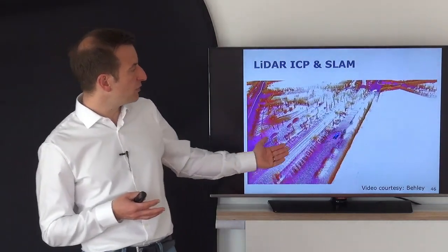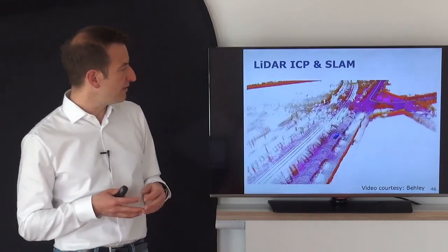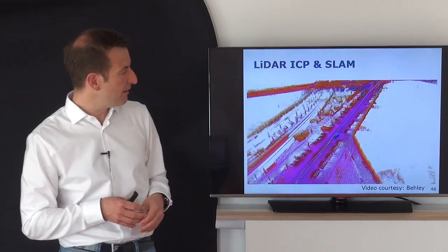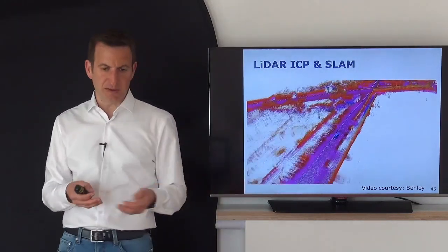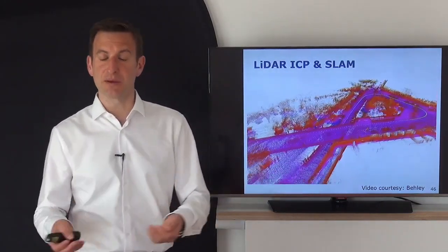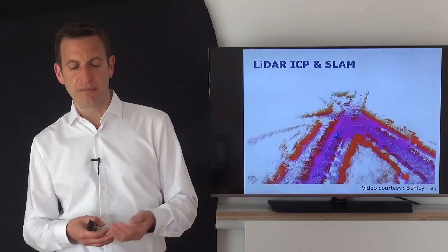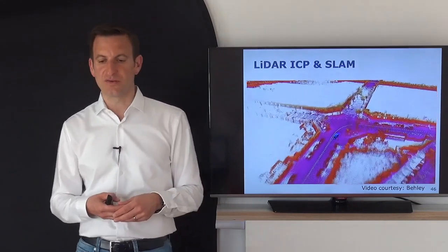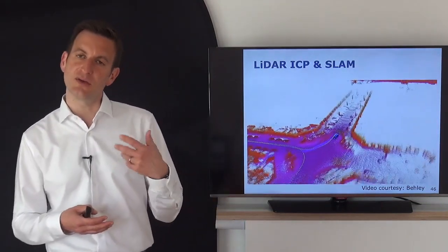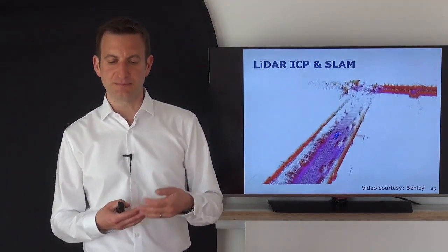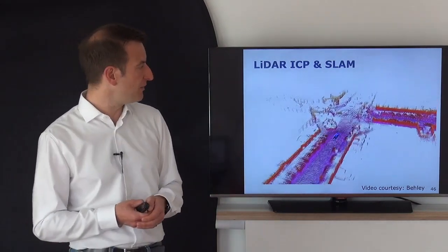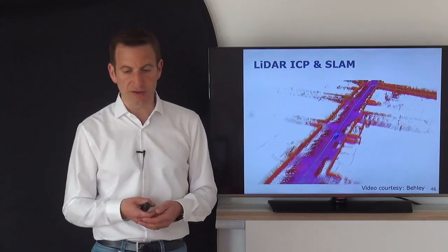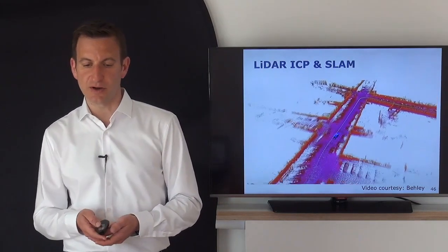And now you can see the robot re-enters a known part of the terrain, and then you will see the SLAM system kicking in and doing some corrections. So you saw the map shaking a little bit, and this was an optimization due to the pose graph, something we will look into later in that course. But most of the registration you can actually see here was done using the ICP algorithm. So you can build consistent maps over extended periods of time using this technique, and it's a key ingredient for a lot of those SLAM systems which are actually out there.